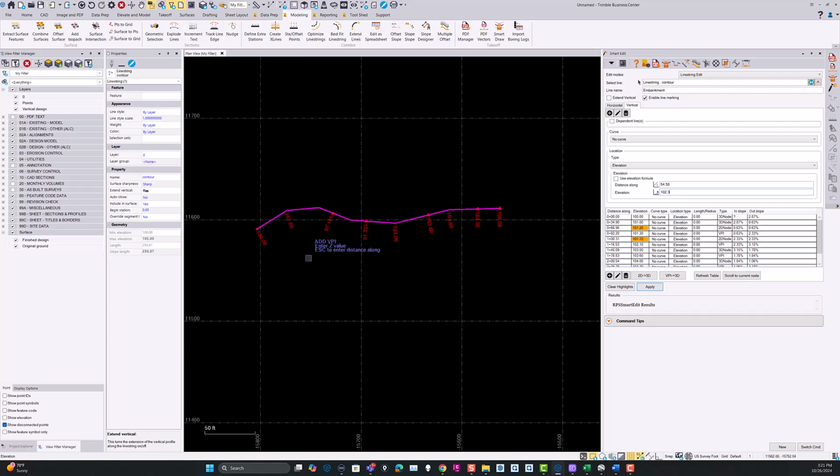and now you can add the elevation. If you're in edit mode here, now you're going to be in the opposite mode, which is now you are being asked to select a node or a VPI location. So if I click this one, as soon as you click it, it's in the elevation mode over here. You see I didn't have to touch anything over here, and it's already ready to change. So I can do 101.3 and press enter, and then I can edit another VPI. So let's say I click this one and do that one as 102.4, and so it's very easy to click on a node and change its elevation.